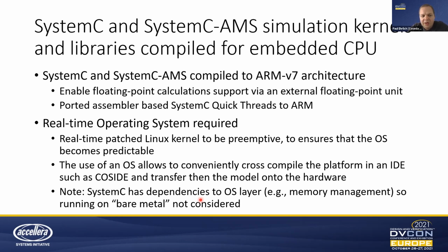If you go for an operating system, make sure it's preemptive. This means if a system thread gets executed, it has to be interruptible as much as possible, because you want to have a precise return time for your threads running the simulation. If they don't do the calculations in time, your hardware in the loop will fail.